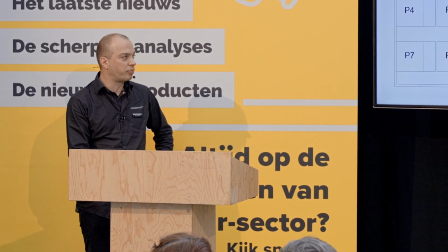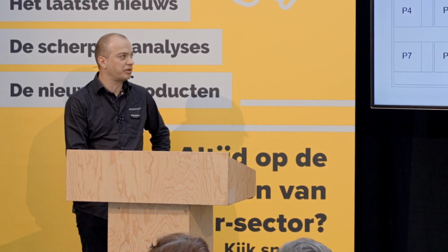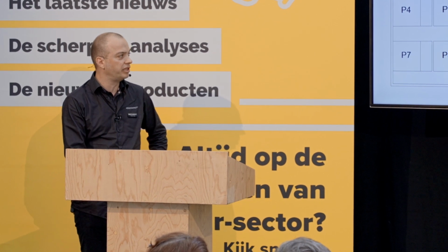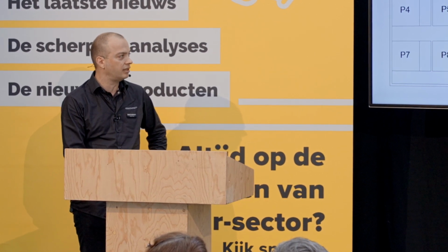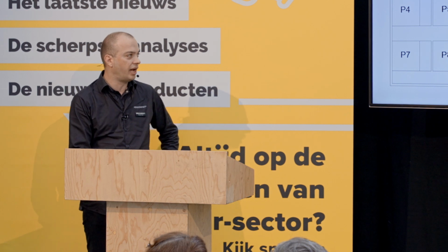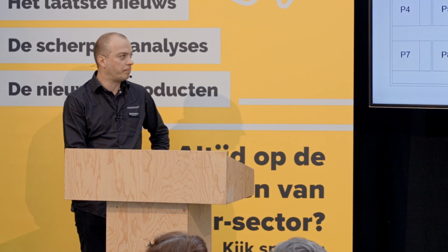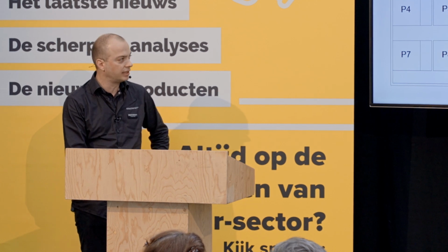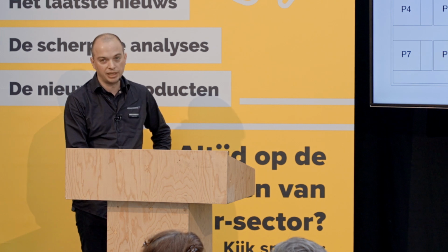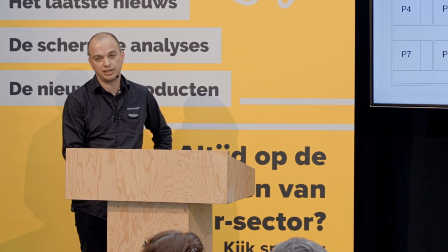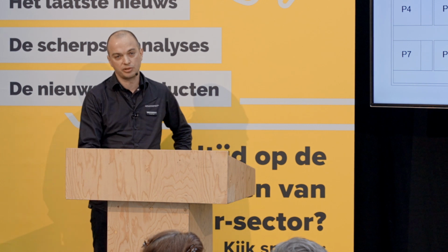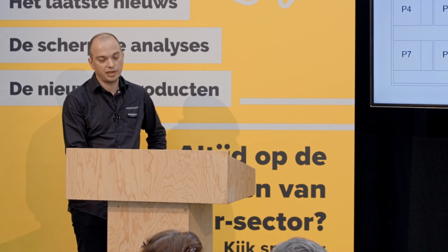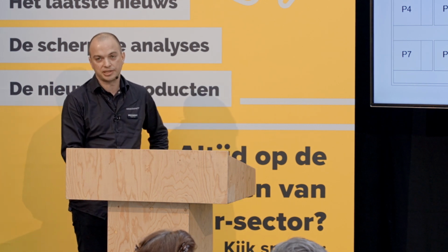It's also important to test for different building sizes, so usually we go for different building plan dimensions, varying the height. Parapets also have an effect on pressure coefficients. Sometimes you can test for roof slope and sometimes even for open buildings, but in general enclosed buildings are tested because that is conservative. By enclosed I mean buildings with walls on all sides.